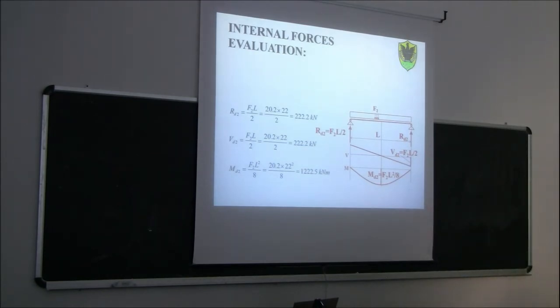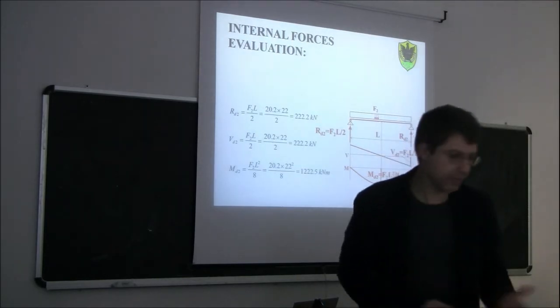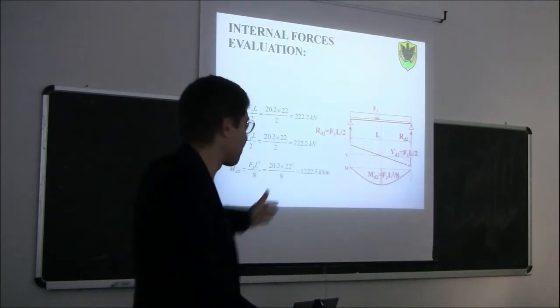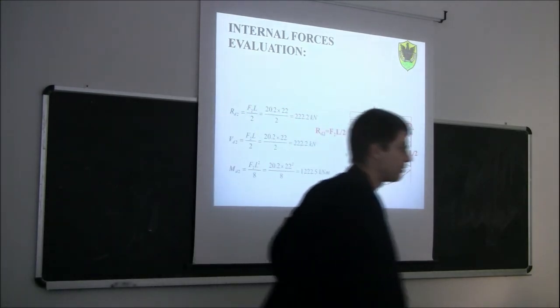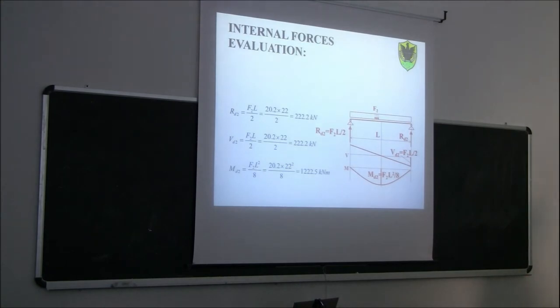Okay, now if we were designing with reinforced concrete, what would you have done? Or what would you do now? Let's say, what would you do if you arrive at this point? You have to design a reinforced concrete beam, like this. How would you follow up? Well, this we have already done, so you should know what to do. Design for the maximum value of the moment. Exactly. You will design first for the maximum bending moment.